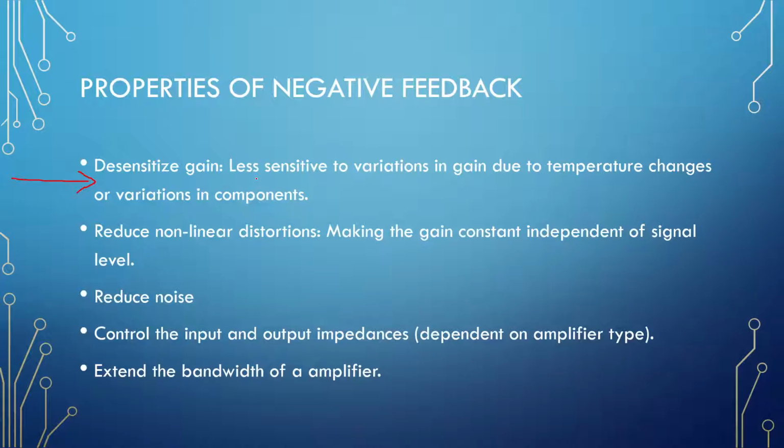An op amp is a bunch of transistors, and you can buy 20 of them, and not one of them will have exactly the same gain. But when you apply resistor feedback to them, they will all produce the same output, the same gain. So feedback is to make processes a little bit more precise. Feedback is one of those things that can fix a lot of problems that you have with your analog electronics.